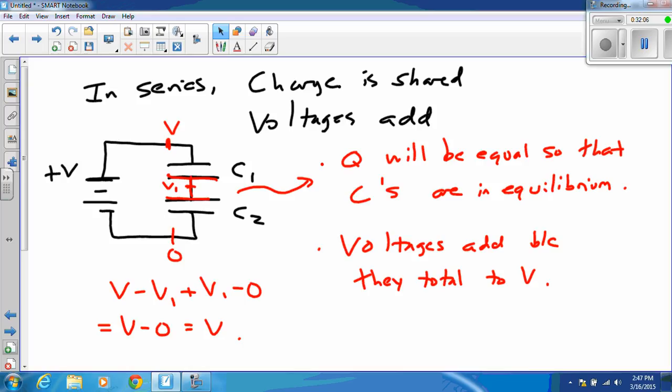So what do we have? We have one capacitor hooked up plus to minus, hooked up to the negative power bus, 0 volts at that end. Then it's connected to the second capacitor, which then hooks up to the plus V all the way back here. So the connections are the same as the connections in that diagram. Does that make sense to everybody? Okay, now let's turn it on and see what happens.